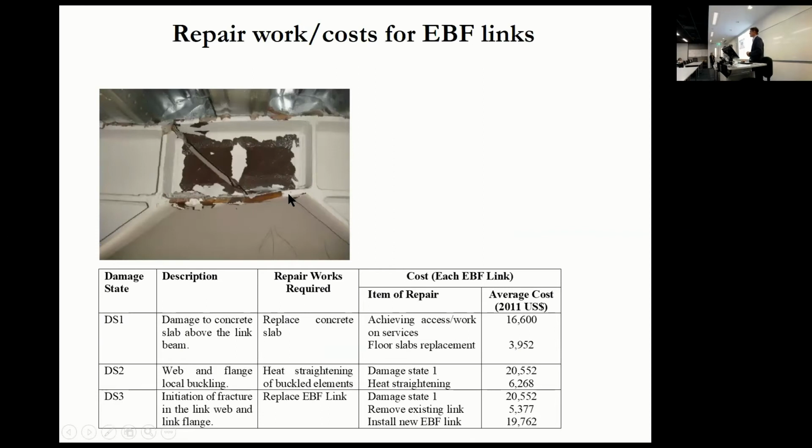undergo inelastic deformation. This particular link has undergone too much inelastic deformation and it's fractured, but ideally you would see just maybe the paint cracking and you could repair that. You could repair this anyway, you have to cut it out and put in a new section. But okay, so we had damage to the links all the way up the height, and you would say for this sort of earthquake event, which was a rare event, this is expected.